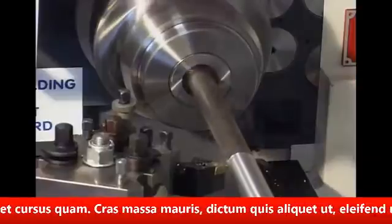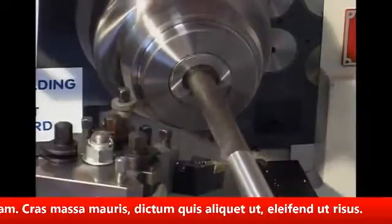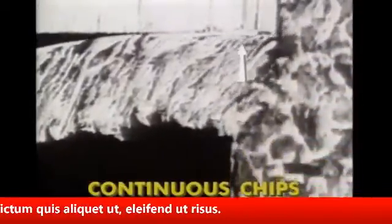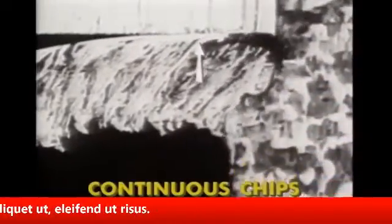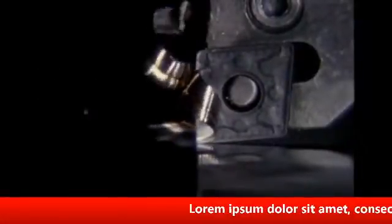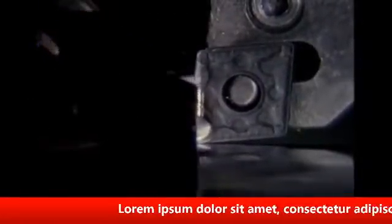The goal in machining is to achieve the most efficient separation of chips from the metal workpiece. The edges of the cutting tool, driven by the power of the machine tool into the workpiece, force grains of the metal to move away from the advancing cutting edge. This displacement causes the metal to fail. A chip forms along this line of failed metal, which separates from the work material.